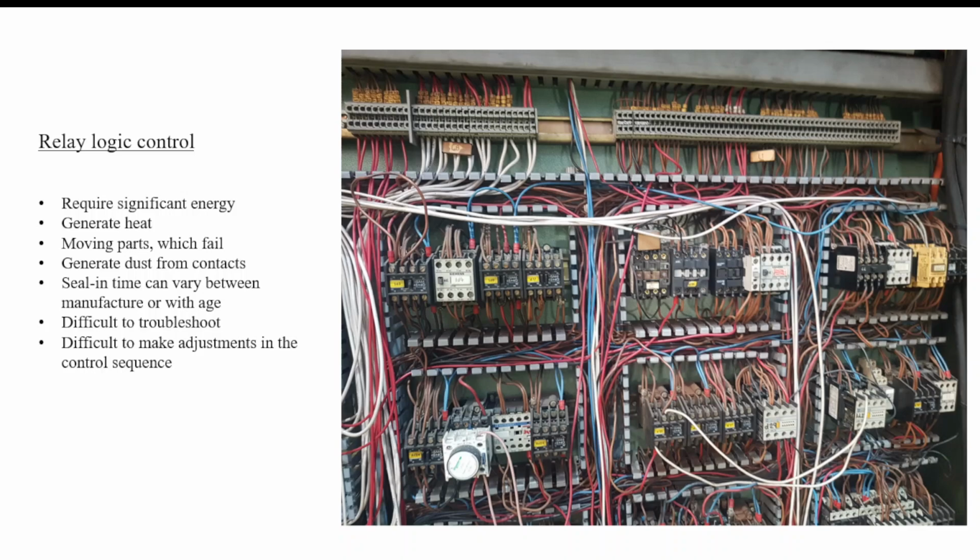Relay control logic requires significant energy, generates heat, and there's moving parts. There's the armature and the contacts, and they fail. It generates a lot of dust from all the contacts that are opening and closing and the arcing that occurs. The seal-in time, as in how long it takes this relay to fully seal in versus this one, will be different. And that difference will be based on the manufacturer, the brand, and the age of the equipment.